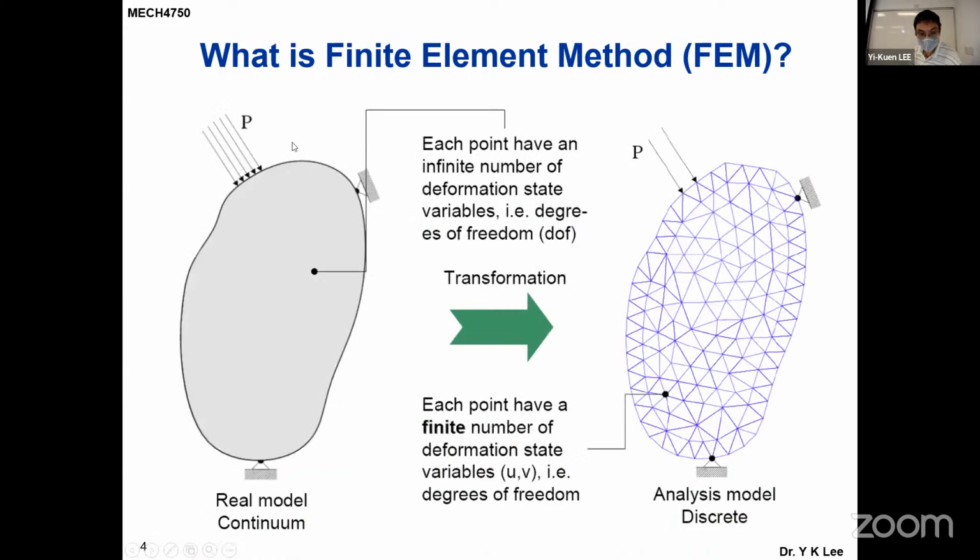Basically, for our mechanical part, you have this kind of geometry, like our unmanned ship, apply the loading, and then we discretize this very complicated three-dimensional product model into, maybe, triangular elements. We use a finite number of elements to describe this more complicated three-dimensional design of your product.